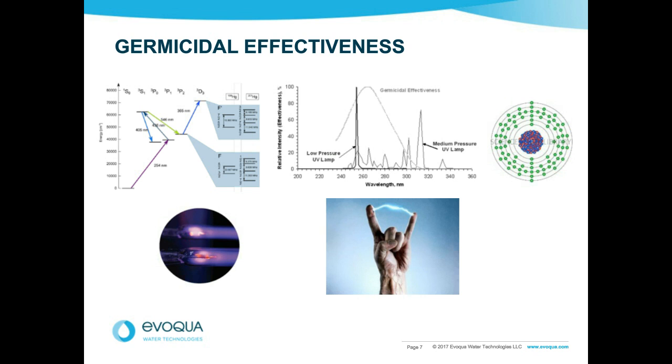Next question involves reverse osmosis again. Have UV systems been used effectively as a pretreatment step in front of reverse osmosis systems to economically prevent, reduce, and control biological fouling of the RO membranes? They have, yes. It's a pretty well studied case, a well documented case. We have lots of examples of exactly that.